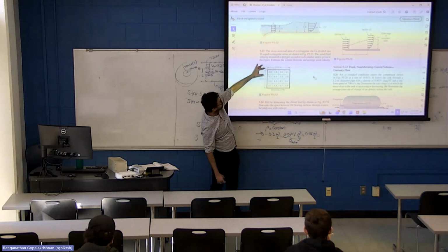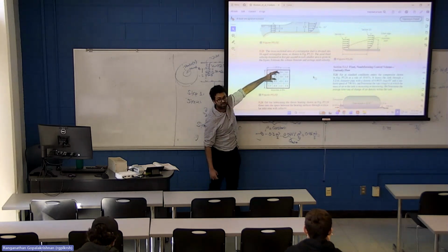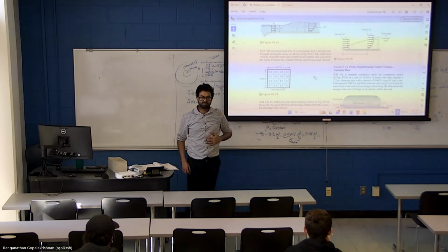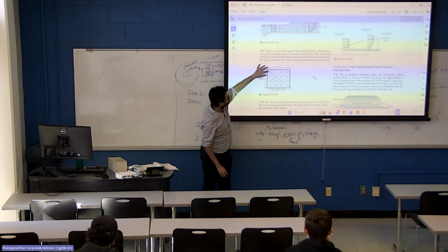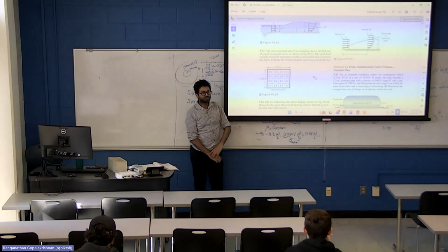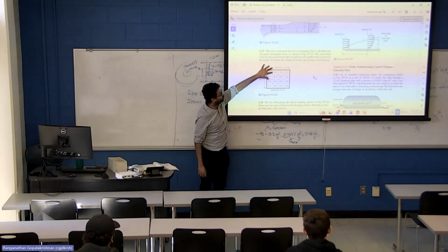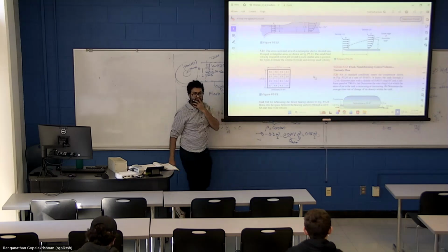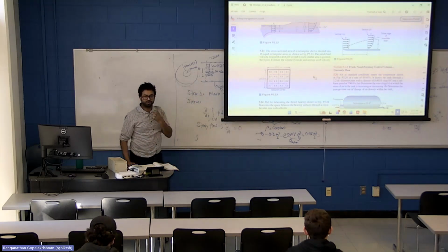And then you estimate the flow rate in each segment and sum everything up. So what is the flow rate across the segment where you have 3 feet per second? Assuming the 3 feet per second is uniform across the square. Just tell me the expression, you don't have to compute right away.